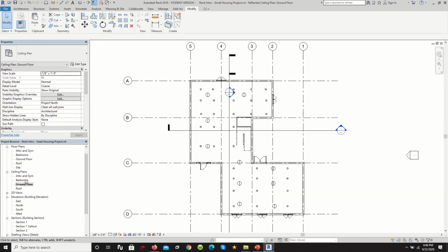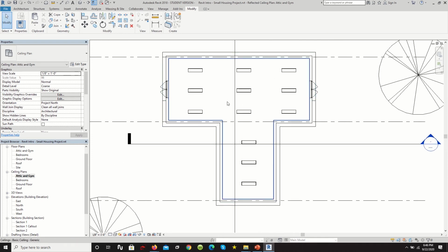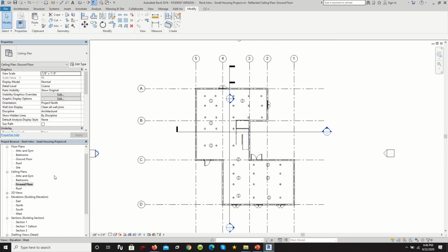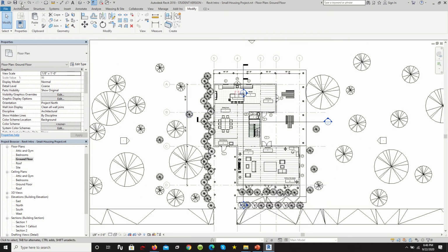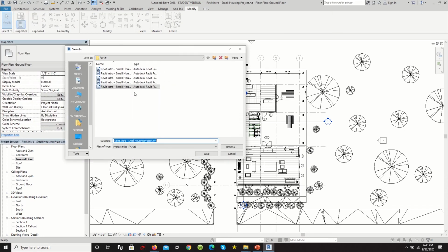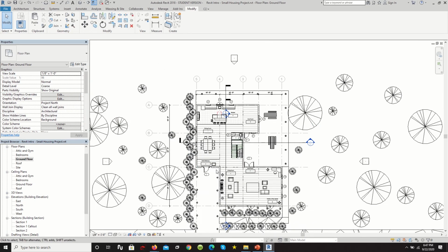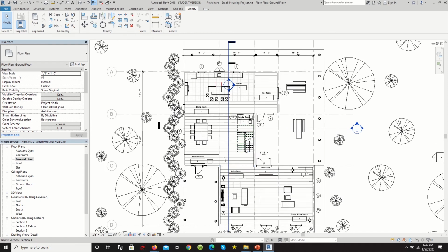And now, once you finish adding all the lighting to each of your schemes, we're going to test out different lighting units to see which one works best, which is why I have different types of lighting. What we're going to do is, let's head over to our floor plan. Always make sure you save everything so it doesn't crash, because when you start working with renderings, it's more than likely to crash. So let's save this. Now from here, what we want to do is actually set up some of our views for the renderings. So how do we go about setting up render views?